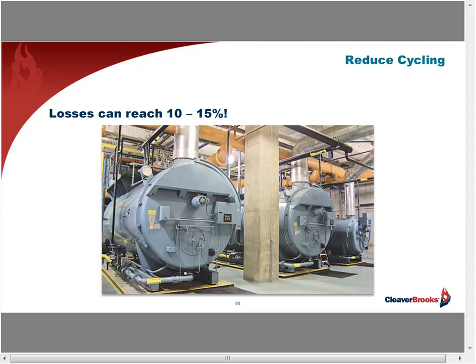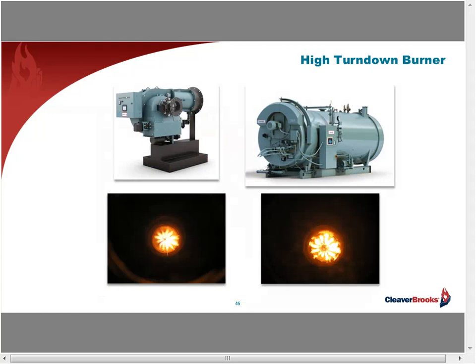If your boiler is cycling excessively, consider a smaller boiler, maybe new or used, or adding high turn-down retrofit parts to your existing burner if it will accept them, or retrofit a high turn-down burner to your existing boiler to mitigate those cycling losses. Payback, believe me, can be substantial, depending upon how much the burner is cycling and, of course, the cost for fuel.